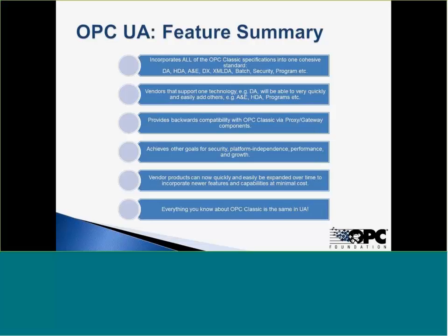Vendors now can support one technology. So instead of having to know data access and alarms and events and historical data access, they know OPC UA, and they just plug in the information models of data access and alarms and condition in HDA. We've got complete backwards compatibility with all the classic OPC products out there.